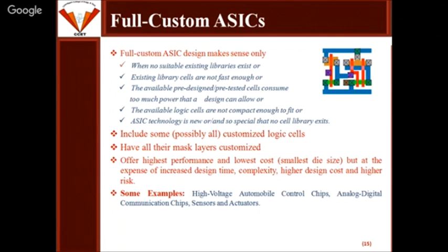Fine. While in the backend, we start from the MOSFET level design, and we define the whole construction of the MOSFET. We can define the dopant level. It means that when we attach the model file along with the simulation, in the model file we define the different parameters of the technology, the different parameters of the MOSFET as per technology. And those parameters are defined by the foundry itself.